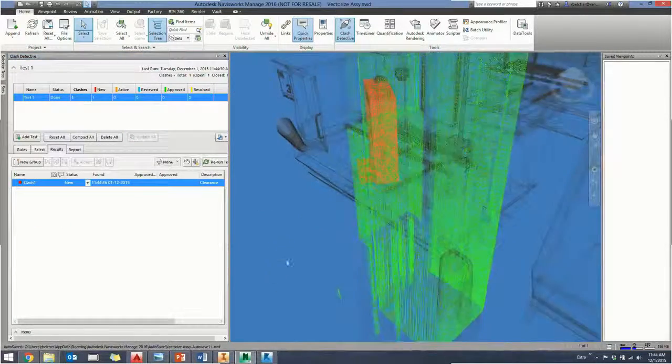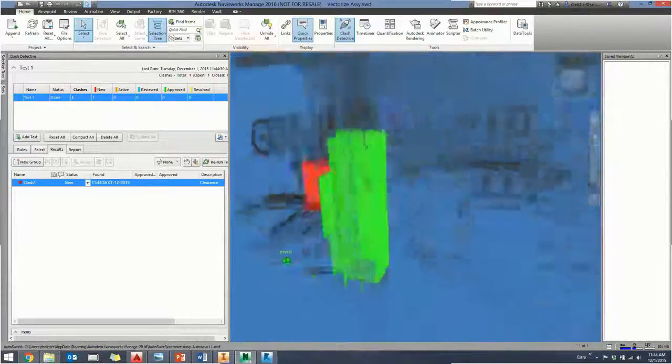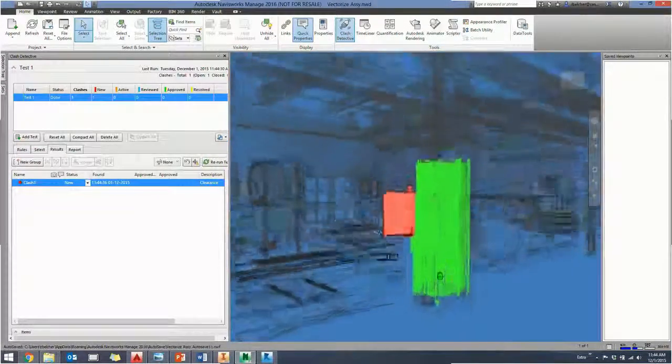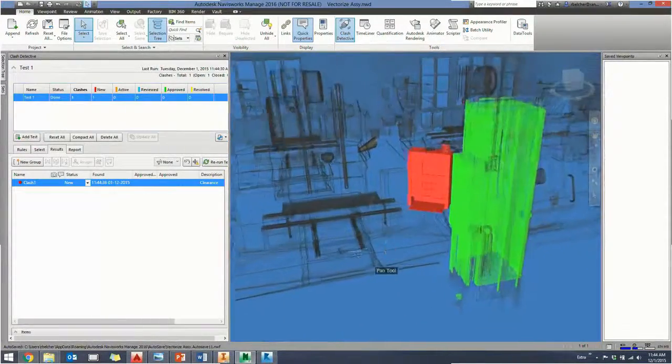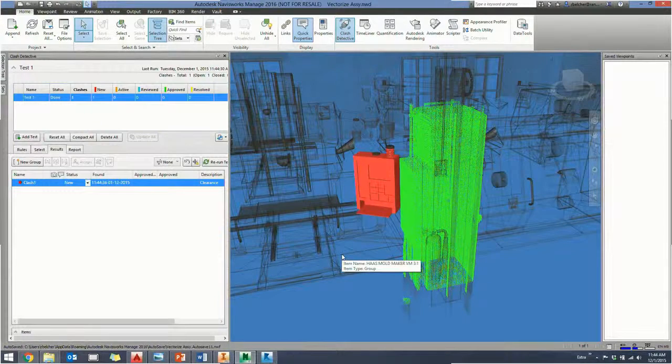So I can run the test. And then I'm immediately prompted where the problems are. So I could tell you right away that the control panel of this CNC machine is closer than 2 inches to the column, to the current setup. Maybe this is a power supply panel on the column. But I know that. Now that I know that, I could write this up. I could go back to my digital design, back over in Inventor, scoot things around, and clear that tolerance.